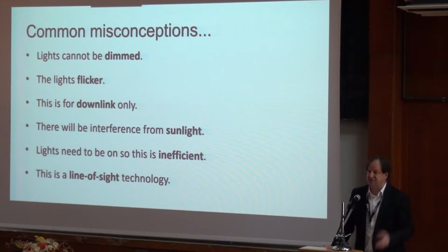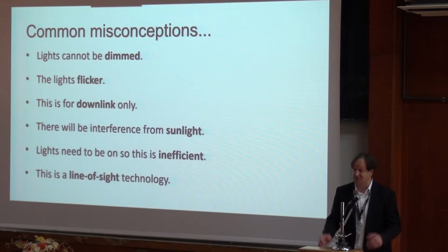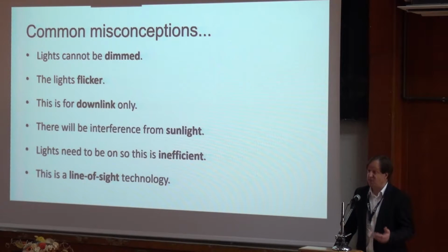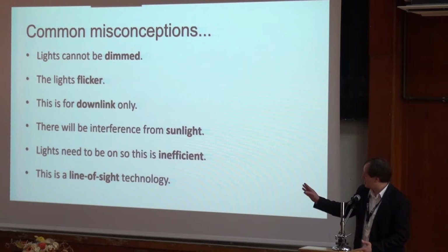There are a number of misconceptions. One is that LiFi cannot be dimmed. That's not true. We can dim it and also transmit data. The lights won't flicker because the lowest frequency we operate at is 1 megahertz, and your computer screen is 100 hertz. You don't see a flicker on the computer screen, so why would you see it with the light? It's not only for downlink, it's for uplink.